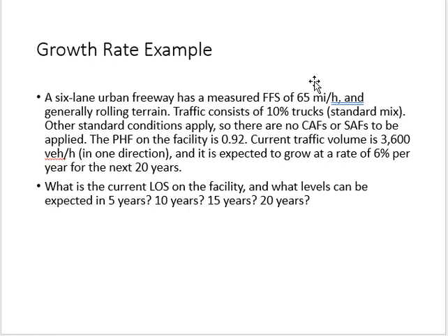What will change? Only the volume. Every year the volume will change, right? Nothing else. So let us calculate what the volume will be after the number of years they are asking for. If traffic increases 6% in 1 year, then how much after 5 years? My traffic is 3,600. It increases by 6% every year. So how much will it increase after 5 years?